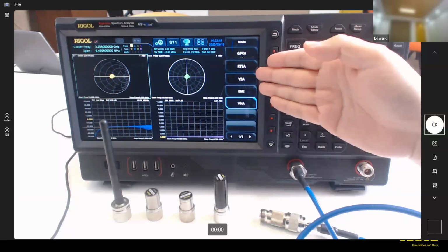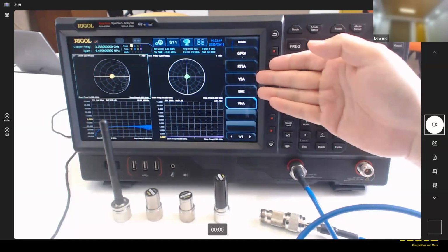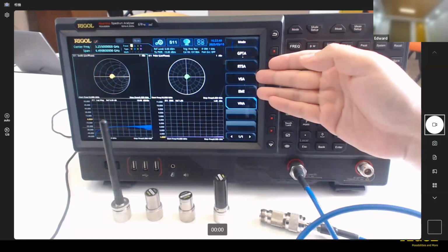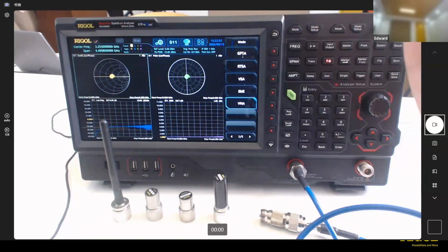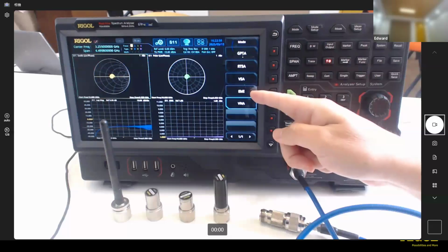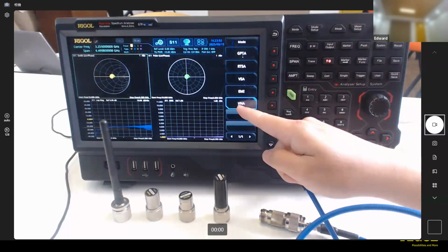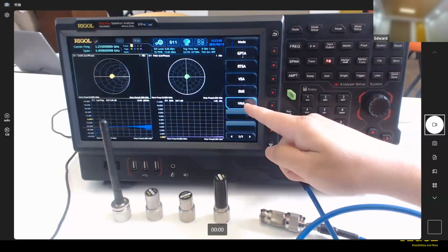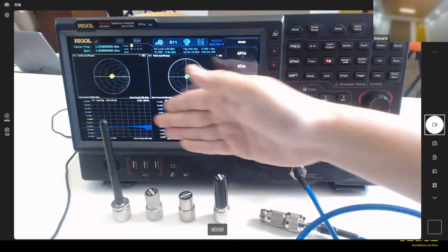You can do some of the demodulation capabilities, such as the constellation diagram, the bit stream analysis, spectrum analysis, and the EVM analysis, because for the constellation you need to verify the error, right? And we also have the EMI, to do the EMI verifications. And the final one is the vector network analyzer, which we need to introduce today for this environment, right?